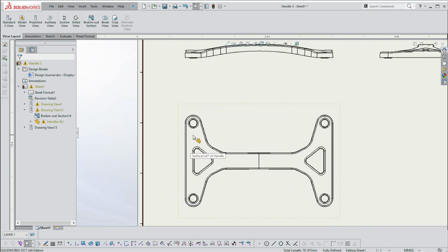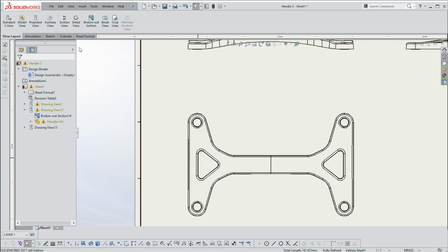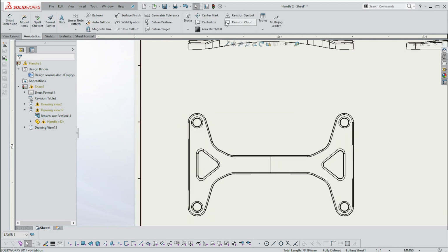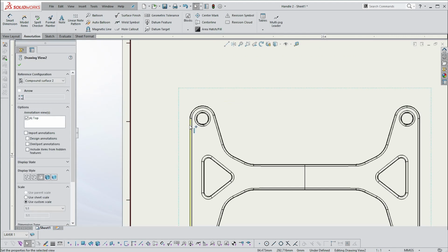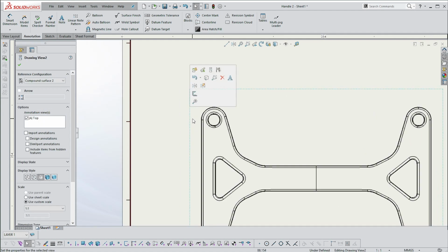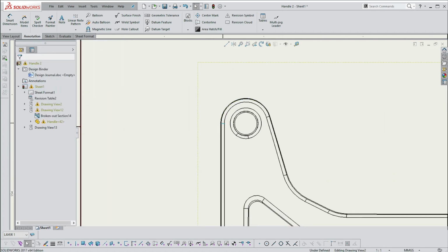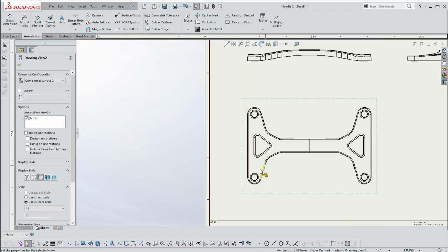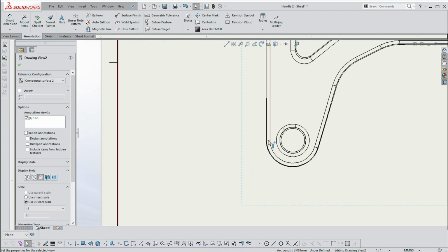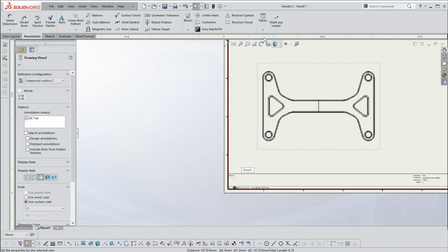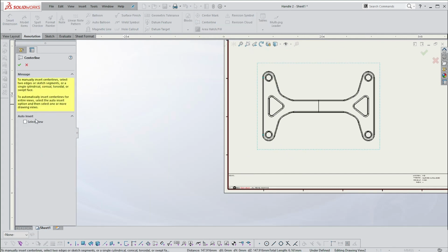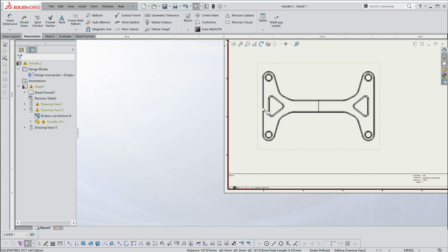Mostly, okay. So the centerline annotation, this one here, not the normal centerline, you can get, as long as you use a feature or part of the drawing which is not going to be part of that compound surface. So these two here are not. So I can go to centerline and I can say select view, and it'll put one in for me. There it is. It's very small, but that's fine. You can drag it out.